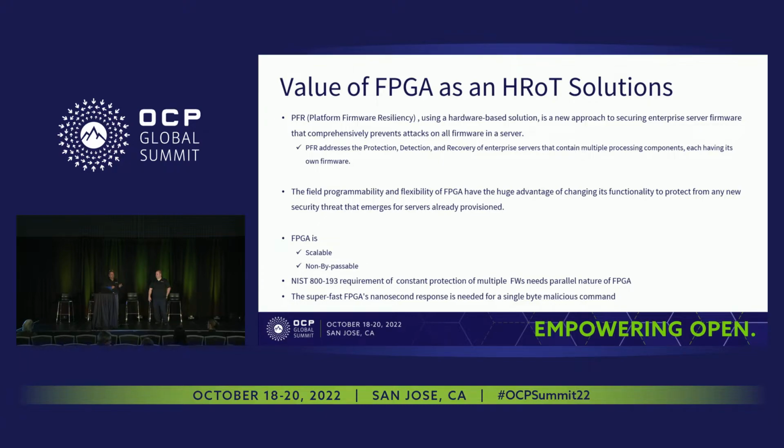That means when you boot up, you try to detect the problem, and if you see any problem, you have an alternate way to recover the firmware. So you're not at the mercy of someone hacking your system and leaving you out of service. You're giving the server vendors a protection and recovery mechanism. That's one of the PFR tenets.